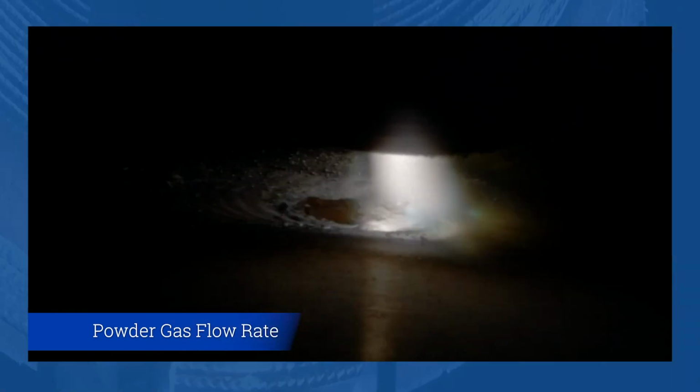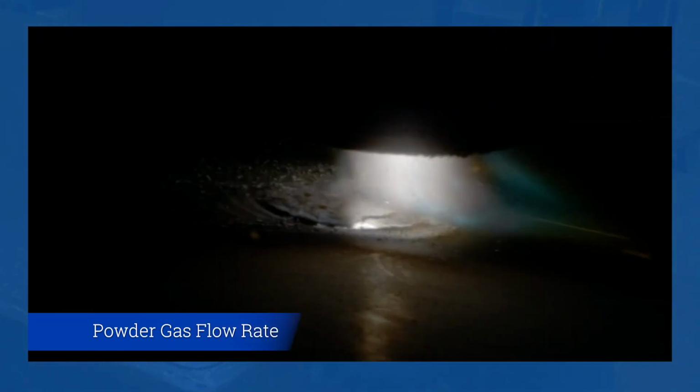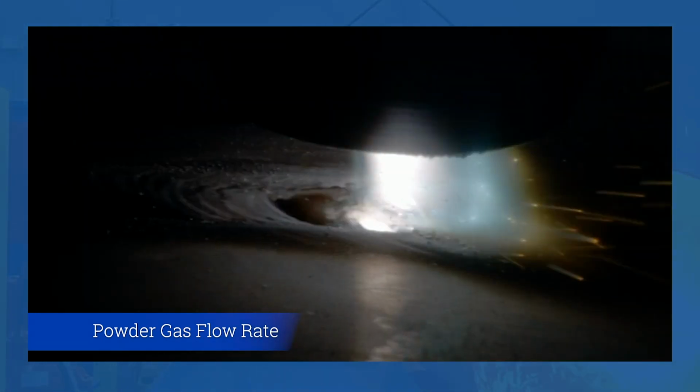Third and final gas flow rate, powder carrier gas. Here everything's set properly. Let's turn it up too high, and we actually distort the arc. We're blowing the arc off the part. We're not getting any fusion, so we're not getting any weld at all. Okay, now we're turning it back down, getting back to the optimum powder flow rate.